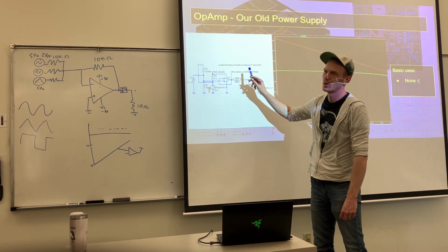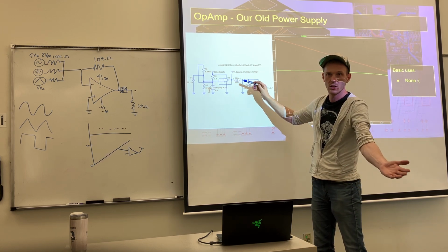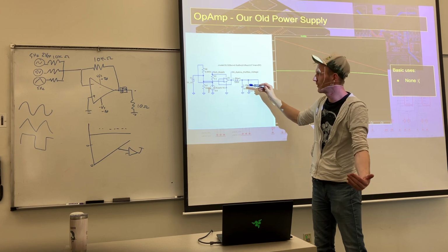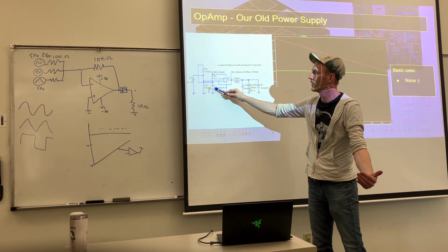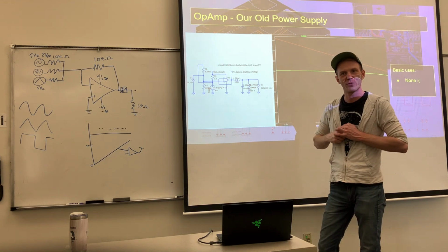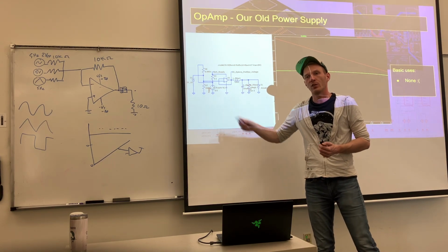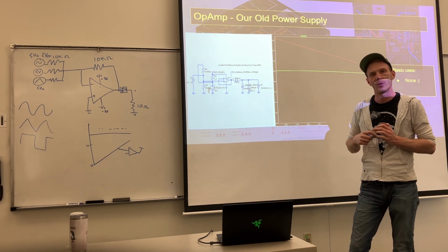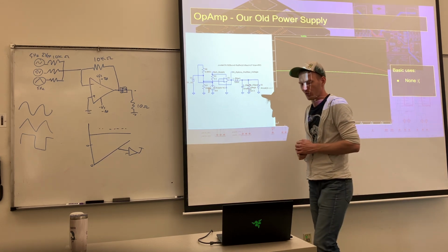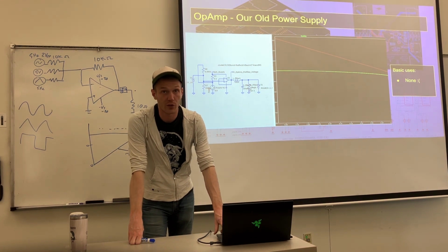I don't think we actually talked about this. You guys remember the boost converter, right? Step up voltages. There's another name for boost converters called joule thieves. They steal energy. If we wanted 7 volts and this was below it, you would have a boost converter to say, well, you're not 4 volts, you're 5 volts, because you want to pull every last bit of energy out of this. We have our 2 in series wired into here, which is why it's a higher voltage than it would be otherwise, but even when they're dead, it's still above 5 volts, so we wouldn't need something like that. Why I chose 2 in series just simplifies the system. Okay, any other questions?